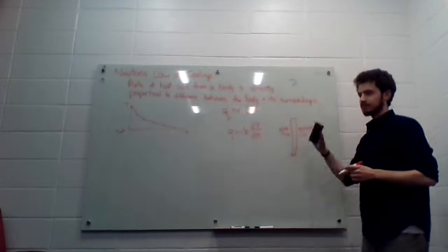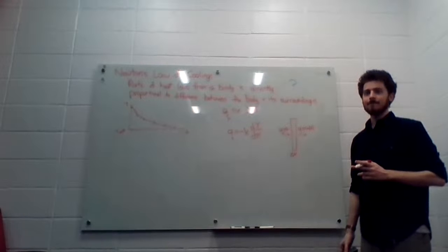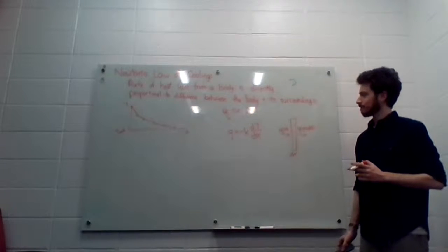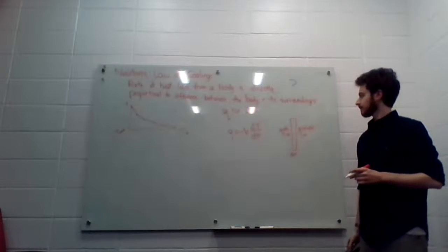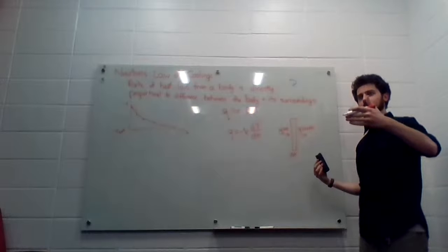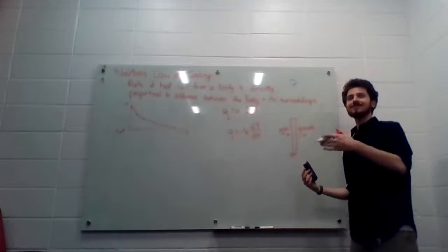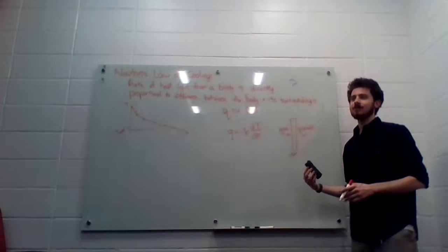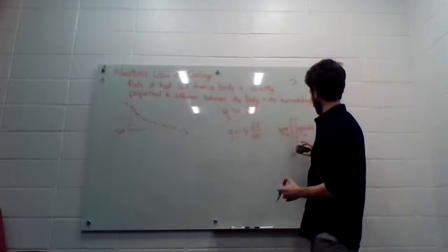So what do we know from this? This will somehow end up equaling that. No, we're going to use this and this together. Yeah. So if you've got a certain amount of heat going through a wall because of conservation of energy, which is useful for some stuff still, what do we know about the other side of the wall? They should be equal. Yeah, it should be equal, assuming there's no internal heat generation, and we're going to assume that for now.